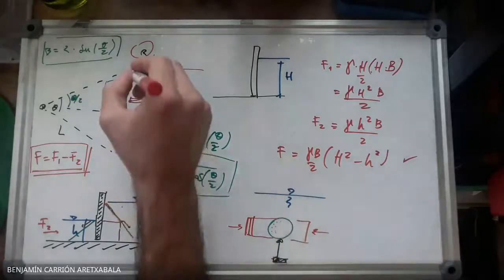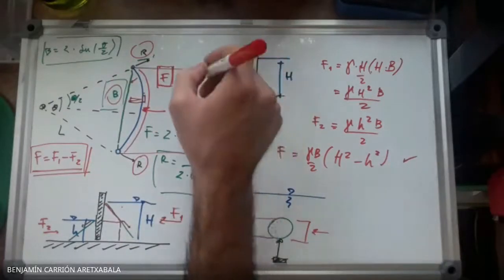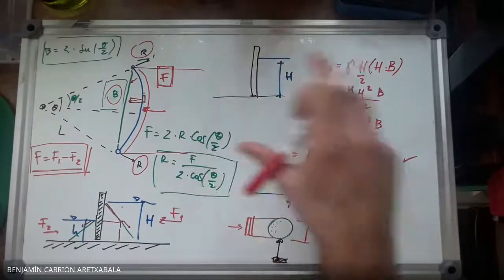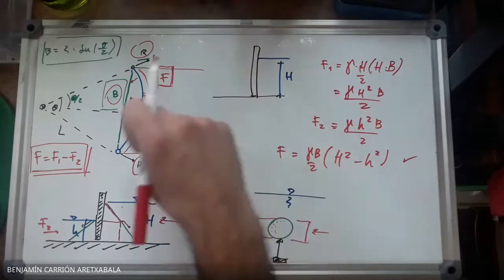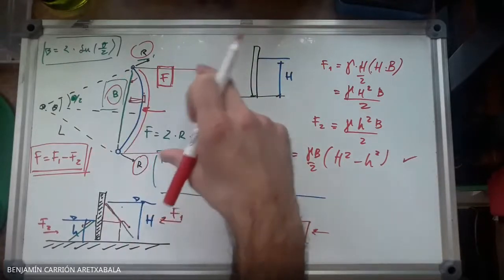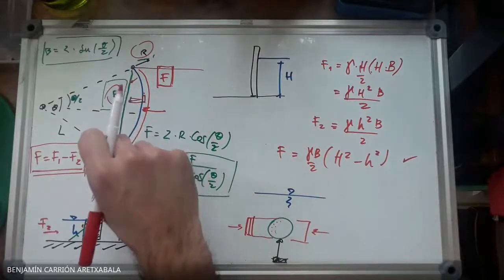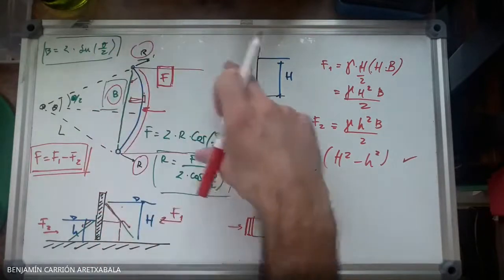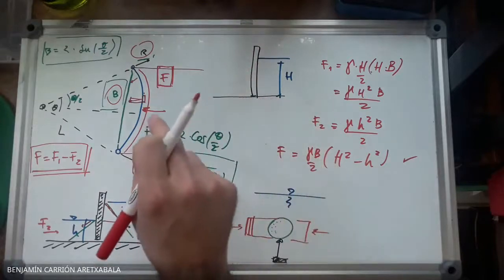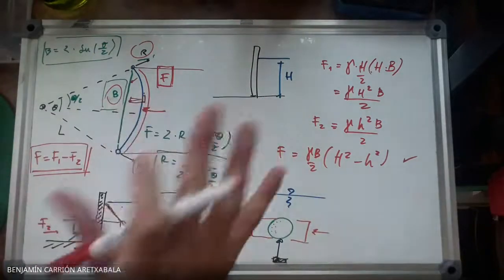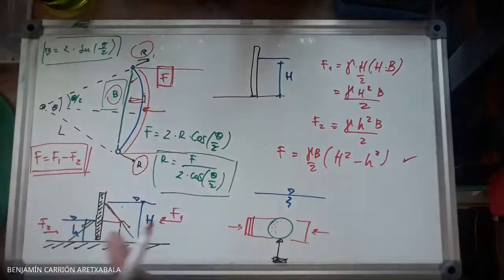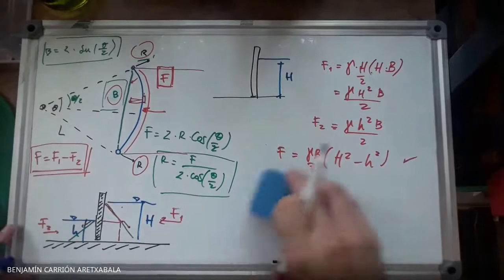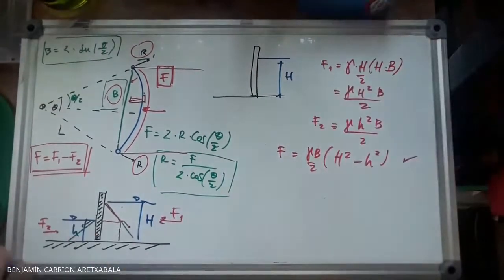So this B comes from, if you look from, in this case, the reservoir or the storm side of the gate, the total width of the gate is not really the width along the gate, but just the projected width. Now that doesn't mean that there is no force, but you need to realize that some of the forces acting on the actual gate are nullified.